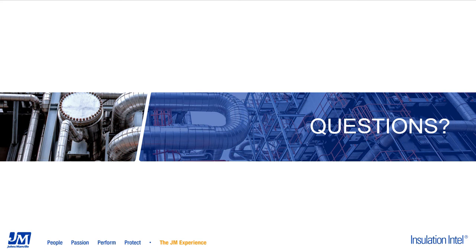I would add that I think Scott's answer is primarily focused at carbon steel. For stainless steel, the lower temperature limit for stress corrosion cracking of austenitic stainless steel is typically around 140 degrees F. So Scott's answer would be completely correct, with the one exception that instead of having a lower temperature, having the corrosion zone be lower, it would be between 140 F and whatever upper temperature number you want to use.